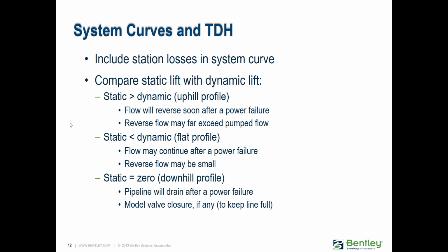So system head curves and total dynamic head, this is probably a review for you guys, but there is the concept of the system head curve when you're dealing with pumps. So the point at which the pump is operating is where its pump definition, its head versus flow curve, intersects with the system head curve. So the system head curve basically defines the downstream system and how it reacts to different flows. So depending on the flow that's entering that system, you have a different amount of head that would need to be added to overcome that. So that's how it finds the operating point and the initial conditions.